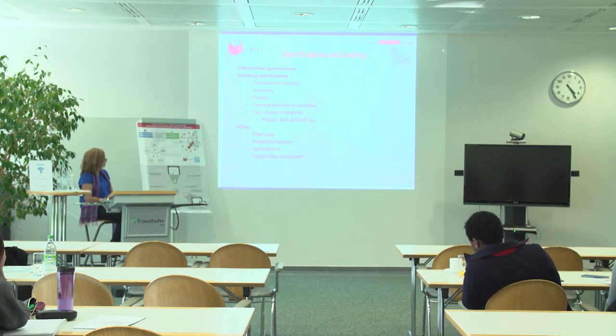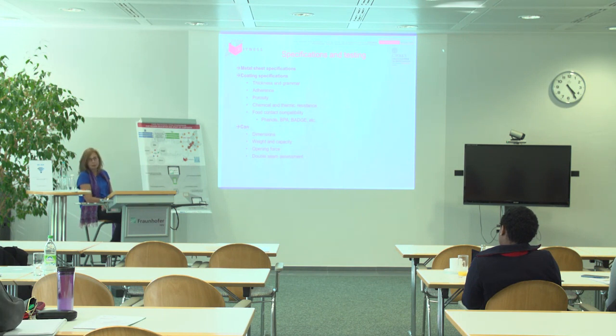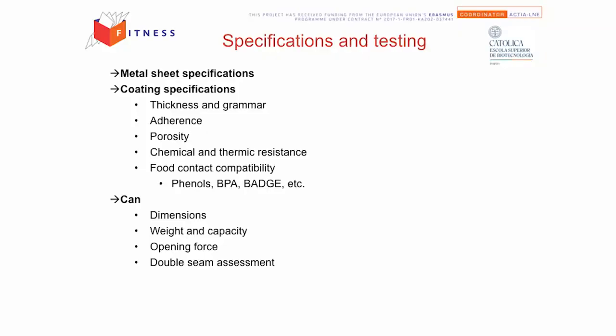And then the chemical and thermal resistance together with food compatibility and migration tests. So migration tests targeting the components of the lacquer, like the phenols that are coming from the epoxy phenolic type of coatings, for example.